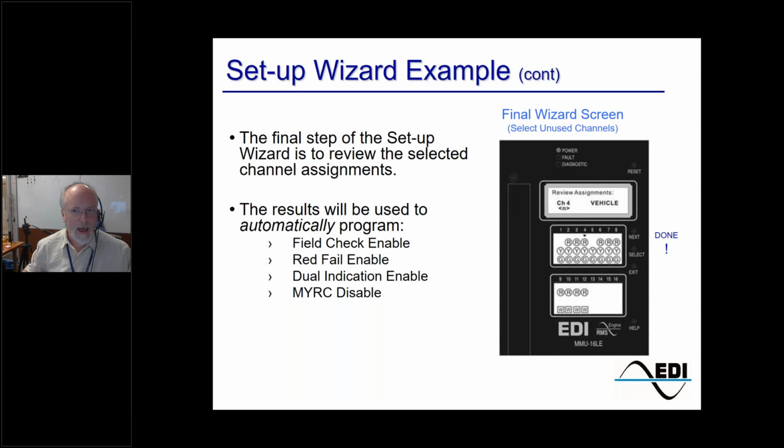I always like to make sure the first thing you do when you get to an intersection, if it's a flashing yellow arrow, is realize, okay, I got to tell the monitor it's flashing yellow arrow. The reason why I say that is when you go through this wizard, if you told the monitor it's a flashing yellow and I highlight over channel 1, it'll say FYA channel 1's paired with 13. It'll tell you that 1 and 13 go together, or 1 and 9.